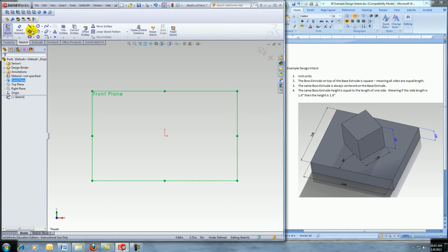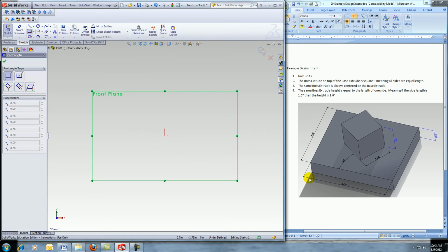So if I look at my options for sketch tools, I have the down arrow here, and what I want is a rectangle. So that one is going to work perfect for me. And you see how the dimensions all come from this corner? Well, that indicates that that might be important. So I'll start with this by simply picking that, and that's my coincidence. You see the yellow symbol popping up on the bottom right of my pencil.